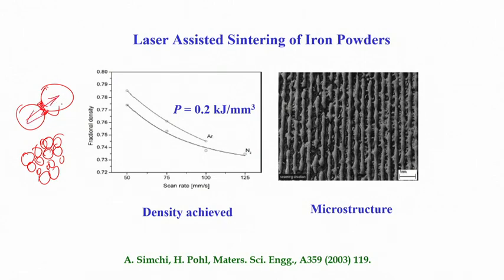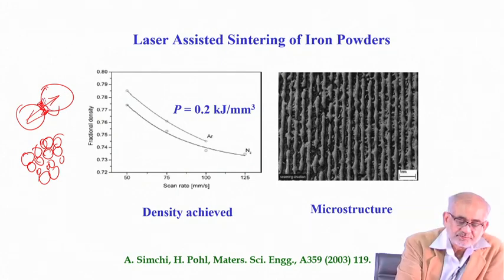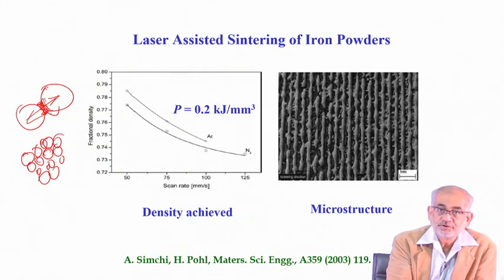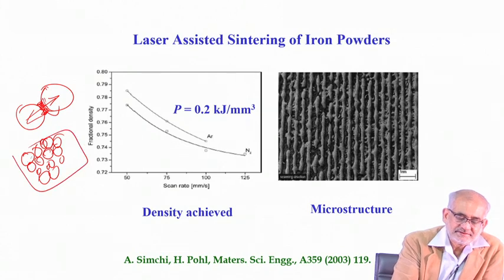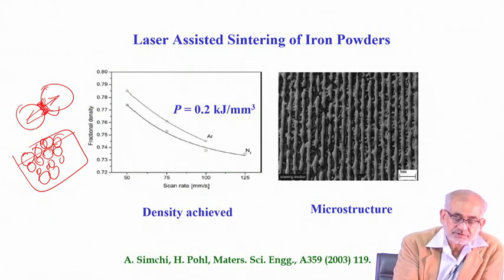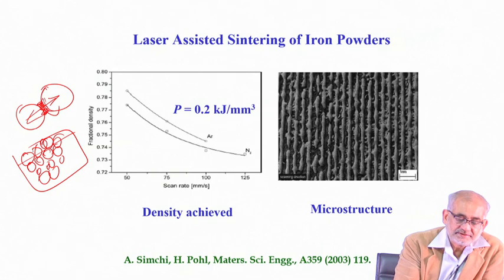So if we are talking about metals, then obviously we want some kind of metallic bond to be formed at this, which could be due to melting or due to purely solid state diffusion. So if you are heating a bulk like this up to a certain depth from the surface, you can do layer by layer, or you can do in a controlled manner such a way that you heat up to an extent so that the surface sees the highest temperature.